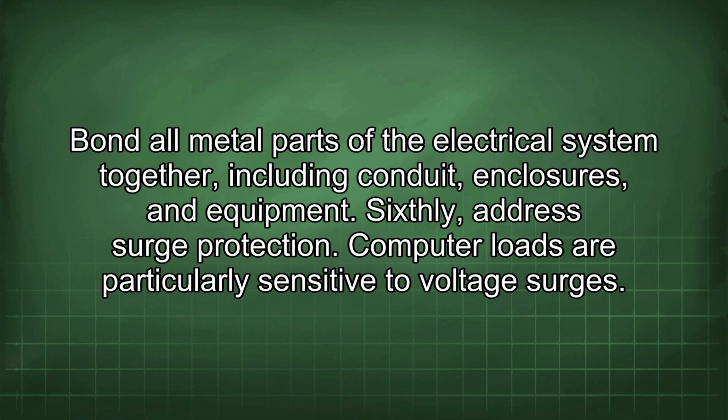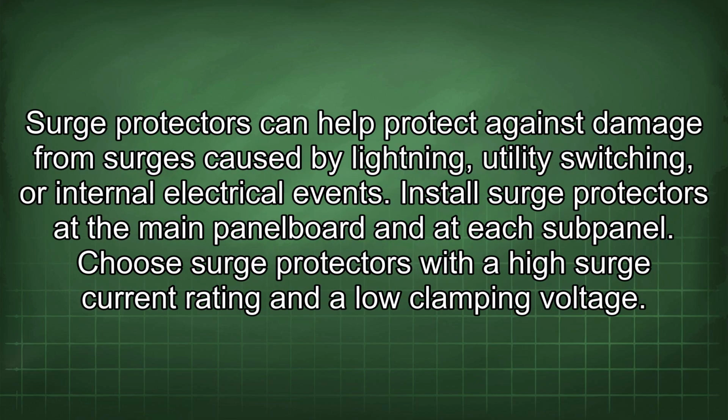Sixthly, address surge protection. Computer loads are particularly sensitive to voltage surges. Surge protectors can help protect against damage from surges caused by lightning, utility switching, or internal electrical events. Install surge protectors at the main panel board and at each subpanel. Choose surge protectors with a high surge current rating and a low clamping voltage.